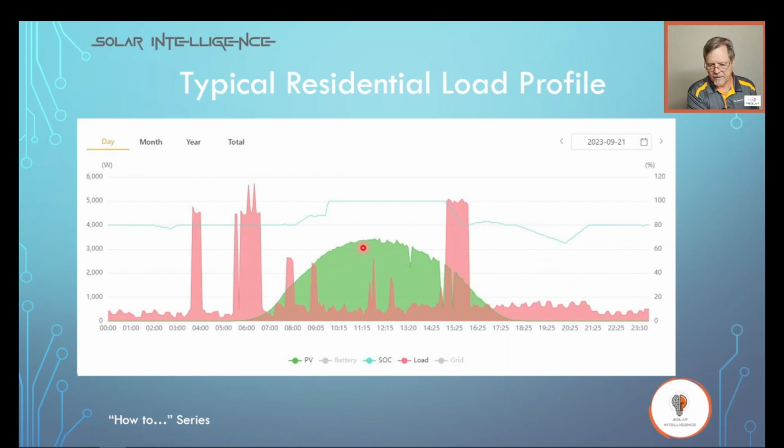And then for the rest of the day, we can see again, as the sun sets towards the west, the angle of the solar panels becomes bigger, the panels get less efficient, and now we've got big loads here, again a geyser and cooking, whatever. Let's look at the state of charge of the battery. Remember the battery was programmed to 80% state of charge. So as the sun sets, there's not enough energy to supply this load. Now the battery is used. The battery state of charge drops.